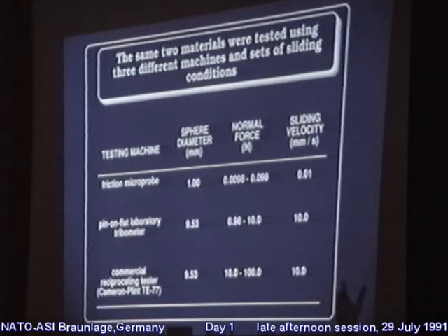And we could play them back and observe the details of the friction trace. With a commercial wear tester, they have kind of a funny way to give you the friction coefficient. Since it's moving back and forth rather fast, they electronically rectify the signal, take the root mean square of that, and then they plot that out on a chart recorder so that they don't overdrive the chart recorder and it can't keep up.